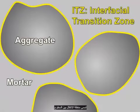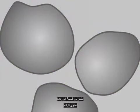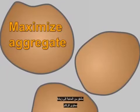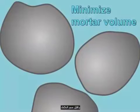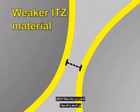In concrete, a very thin, weak layer between the mortar and the aggregate, called the interfacial transition zone, results in very low tensile strengths. Because the design of common concretes is driven by the need to maximize the aggregate content and minimize the mortar volume, the particle spacing is very small, with up to 40% of the mortar volume made up of the weaker ITZ material.